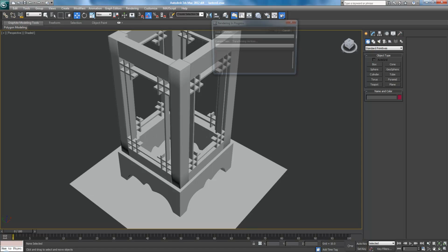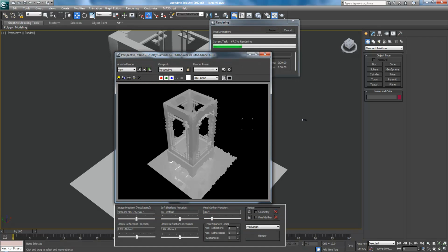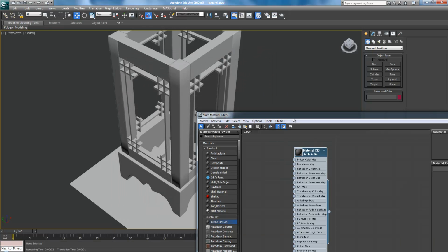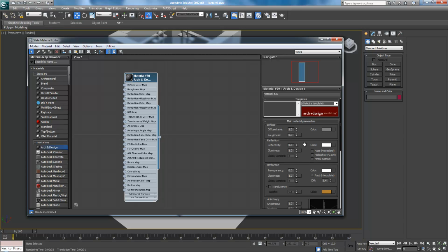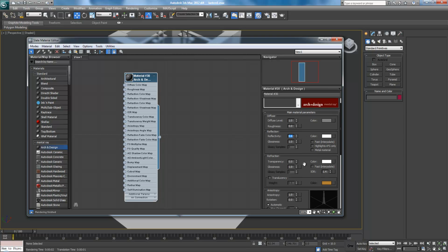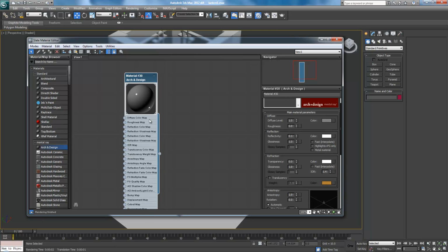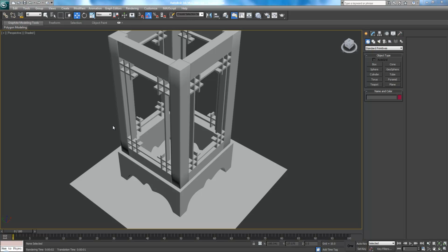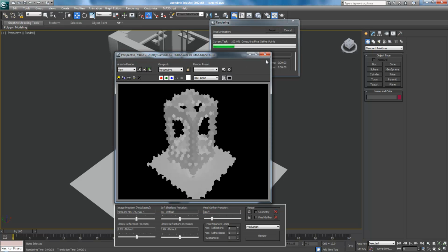And if we render this, let's see. Okay. Go back to your material. I just want to see basically how it reacts. Let's bring the reflectivity to 0.1. So you can see here that made it much less reflective. Let's actually have 0.05. And glossiness, bring it down to 0.44. Looks kind of woodish. Okay, and render again.